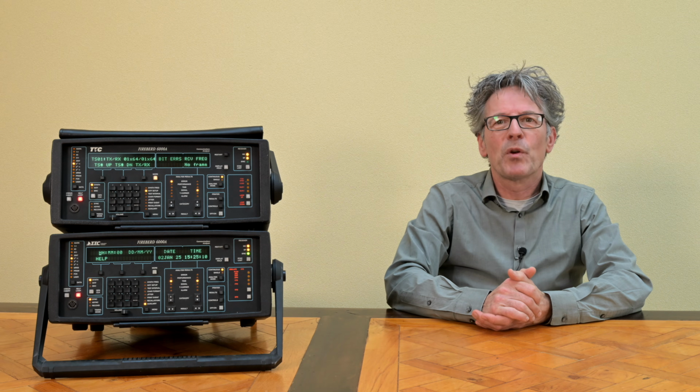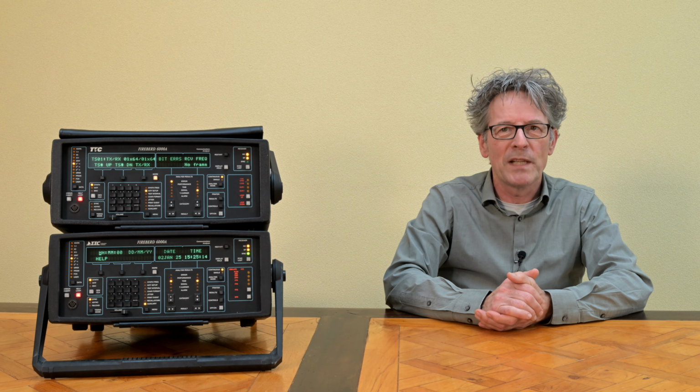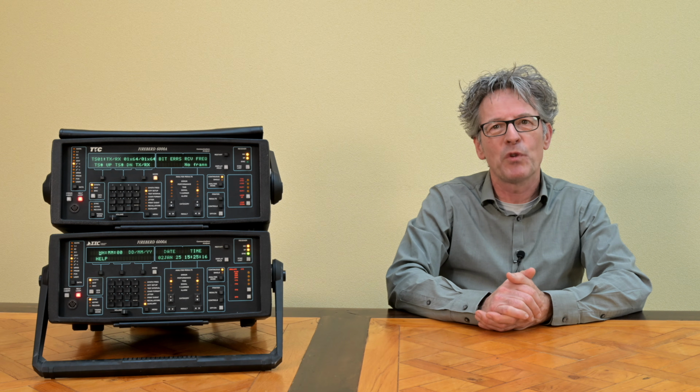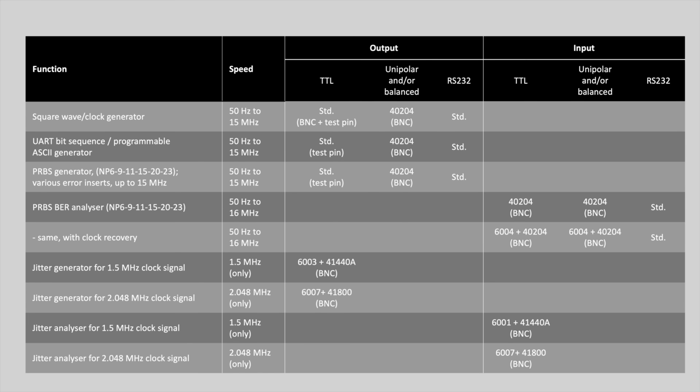Finally, I mentioned a couple of times that depending on what you do, you're going to need some options. So I tried to create an overview of what options are relevant if you want to use this as a generic purpose device. And as you will see here, and I said that already repeatedly, the LAB option is probably something that you want to have, because of the TTL inputs and outputs. The clock recovery option is an interesting option, at least if you want to work with signals where the clock is not available to you anymore.